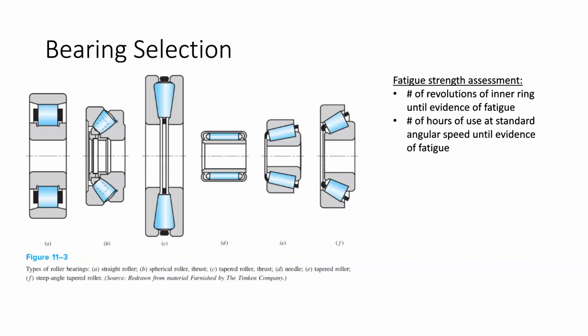So if I were to push radially, I can still support some amount of load because a component of that is going into the reaction against this roller element. But now axially, I also have a relatively large area component, right? So this can actually react axial loads, which again is a system requirement that you would define ahead of time for your wheels. When you corner, there's a lateral force on your wheels. So obviously the bearing supporting that has to be able to support that lateral load, right? That's one example of how I would choose a bearing based on the requirements that I have.